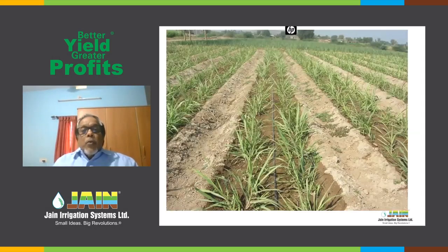Now for anybody who is new to this technology, it is time to understand that the uniform distribution of soil moisture, I didn't say water, soil moisture in the soil at the rhizosphere, that's where the roots are distributed, is our objective. And the objective can be met with an optimum placement of drip lateral to lateral spacing and dripper to dripper spacing, rather than a luxurious spacing which we saw in the first one. And this will obviously be cost effective.